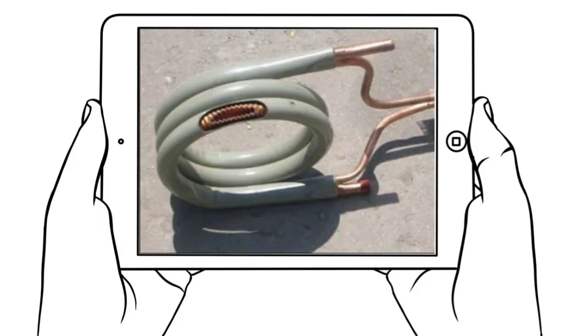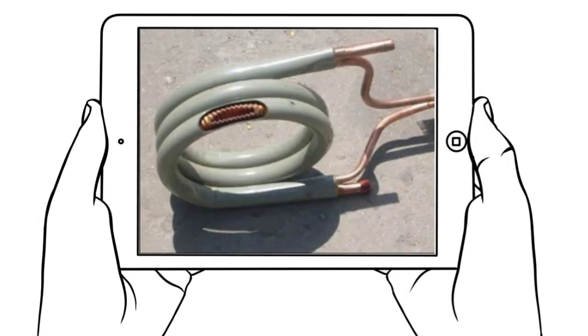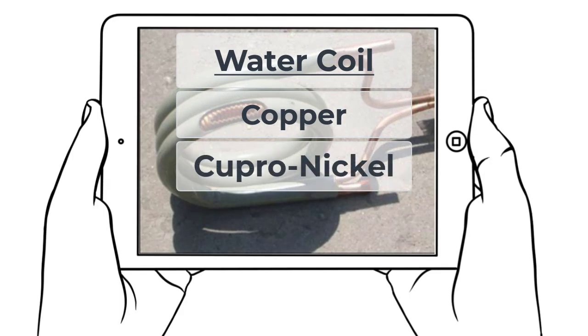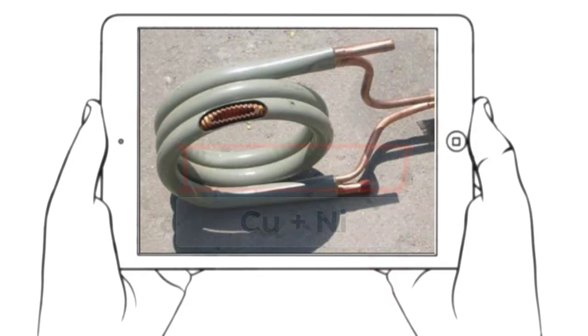The water coil is a coaxial coil, or a tube within a tube, and is made out of 2 possible materials, copper or cupro-nickel. Much like a plain copper air coil, a plain copper water coil is inexpensive but prone to corrosive elements, certain fluid chemistry, too much fresh water, abrasive debris, all of which can severely limit the lifespan of a plain old copper coil. Cupro-nickel is a mixture of copper and nickel, and it is an extremely corrosion-resistant alloy. It's a must on open-loop systems and a safe bet on many others.